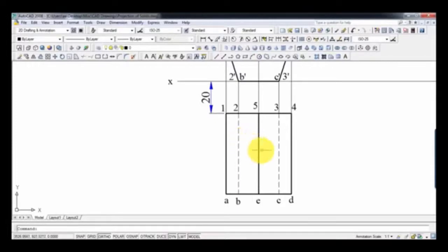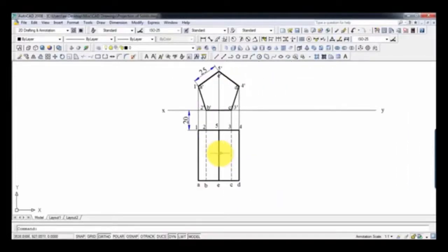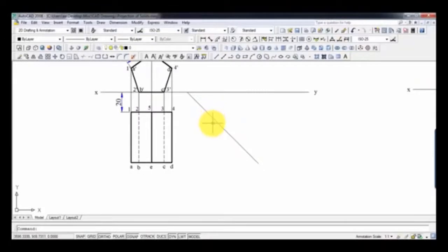Now let's head over to step number 2, where we are going to incline this. Okay, keep this top view at an angle of 45 degrees. That's exactly how this pentagon is going to be kept. This edge over here, it would appear from the top view that this edge is making a certain angle with the vertical plane, and that is in fact, I guess, 45 degrees. All right, if the axis makes a certain angle, then all these edges are going to make the same angle with the vertical plane.